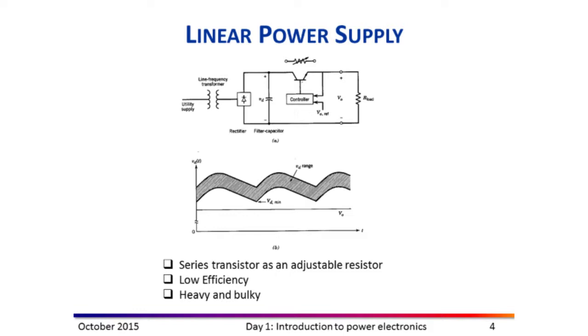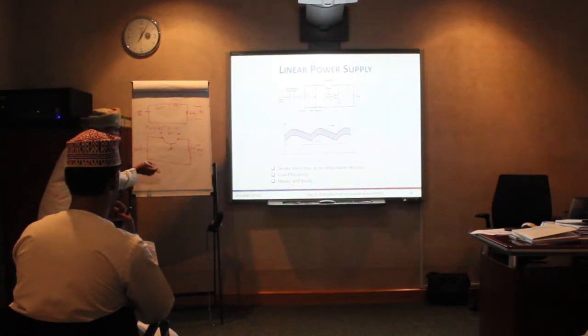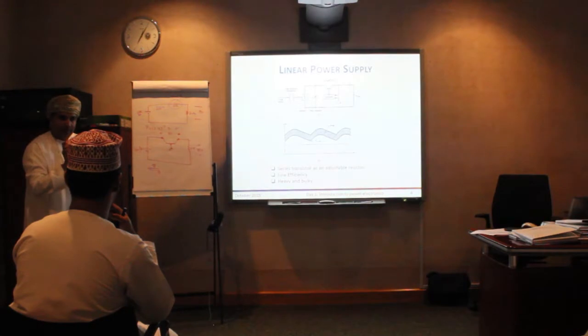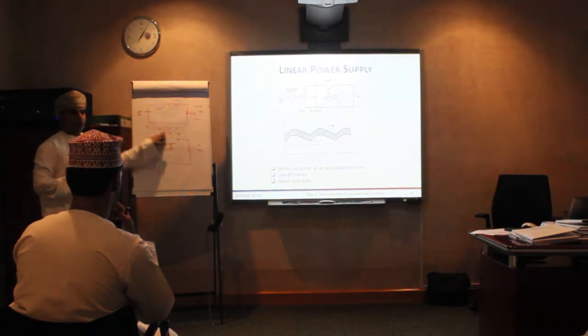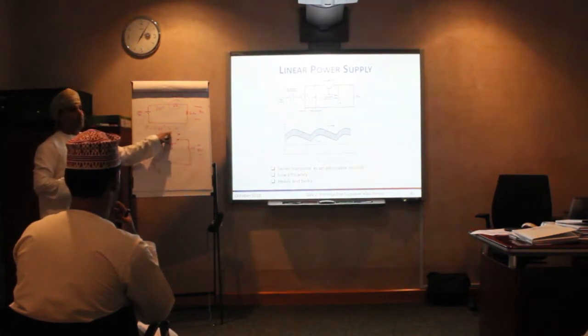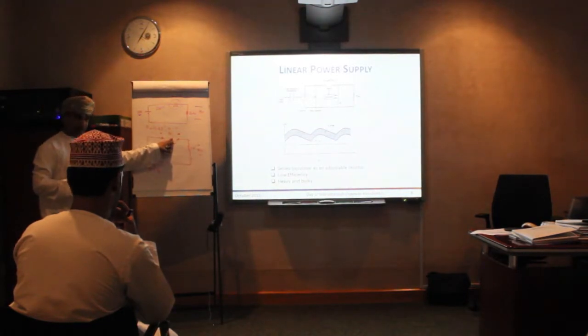Not like this one. Now this one you can look at like a controlled tap of water, and you have water here, right? And then you want the flow of water to be a specific value. You will press that one with a specific force in order to get that water. So in this case you will have some losses here, and in the case of power electronics, where the current is high, it's not recommended because it creates lots of losses across the switch or the transistor itself.